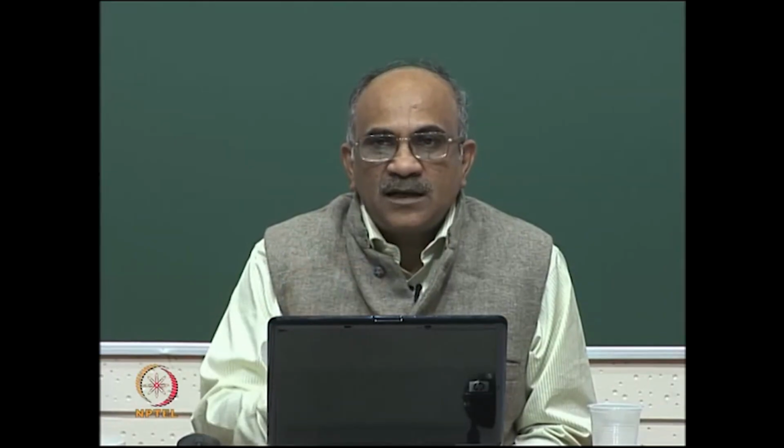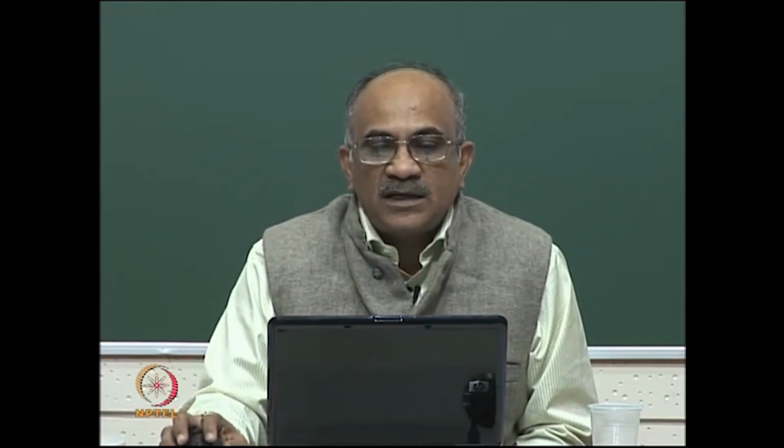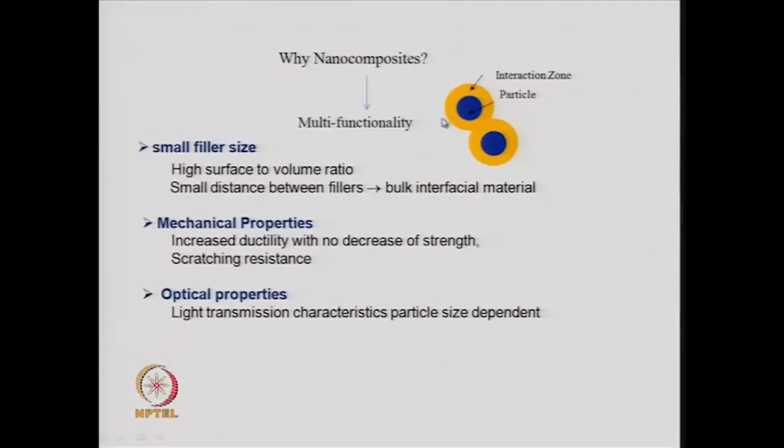If you bring together three materials, then you get a multifunctional material with maybe three optimal properties. Typically you can have composites with particles where one material forms the core and the other the shell, however, you can also have composites where the particles are all separate, but compacted together.